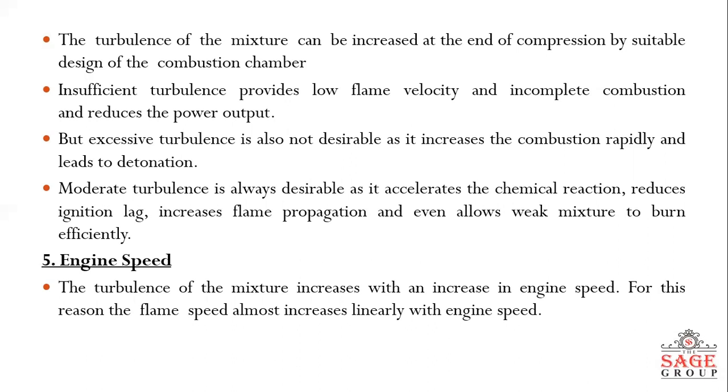It also helps in burning the lean mixture. However, excessive amount of turbulence may extinguish the flame, resulting in rough and noisy operation of engine. A suitable design of the combustion chamber, which involves geometry of cylinder head and piston, may increase the turbulence to a desired amount during the compression stroke.